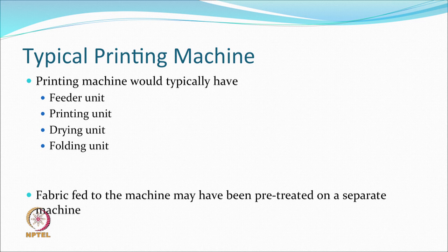So, the fabric, let us say a very lightweight fabric, a knitted fabric, a piled fabric, or something which has a lot of protruding hair, may have to be given a pre-treatment first, so that the surface becomes smooth and dimensions are controlled. Otherwise, you put a little bit of tension and skewing takes place. There can be difficulties in printing and your designs can go haywire.